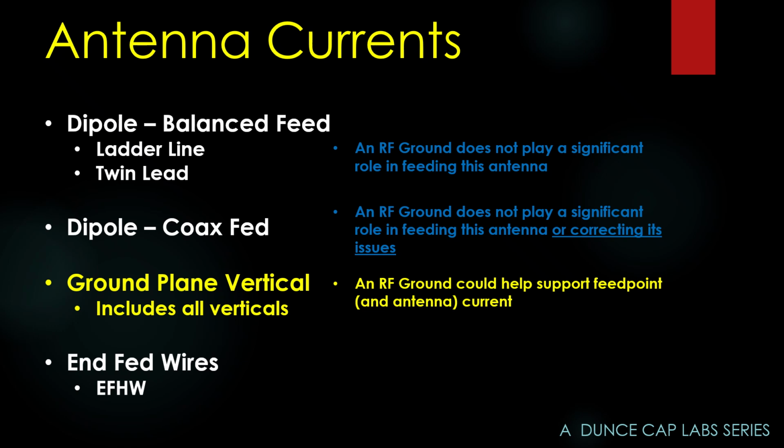So an RF ground could help support feed line and antenna current if we could get enough ground conductivity, which again, especially above about 3 megahertz, that's simply not going to happen.